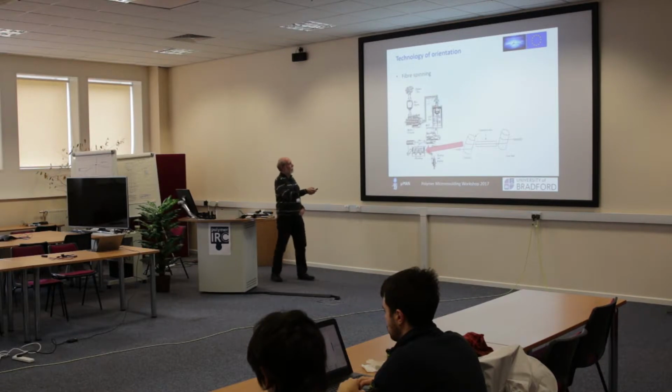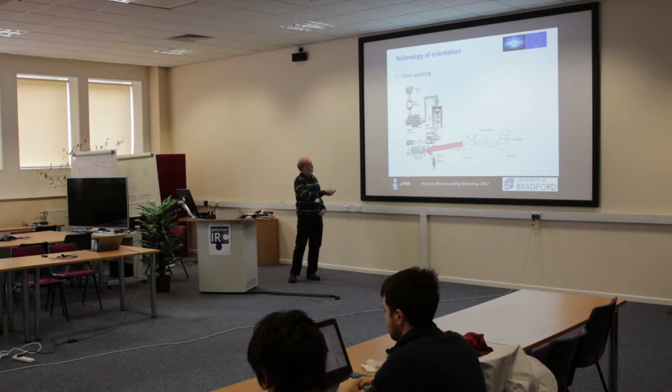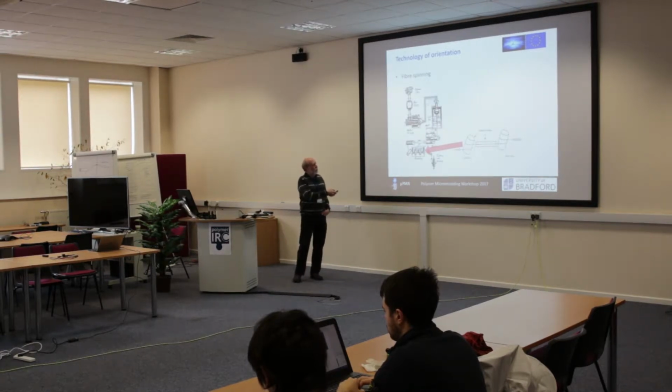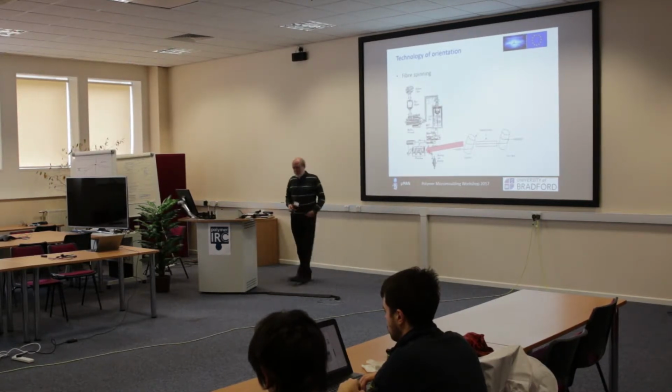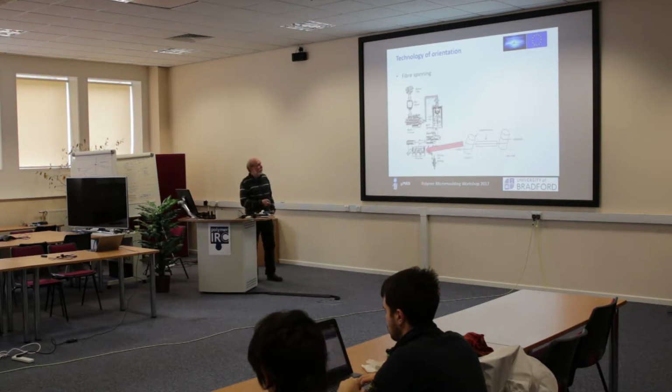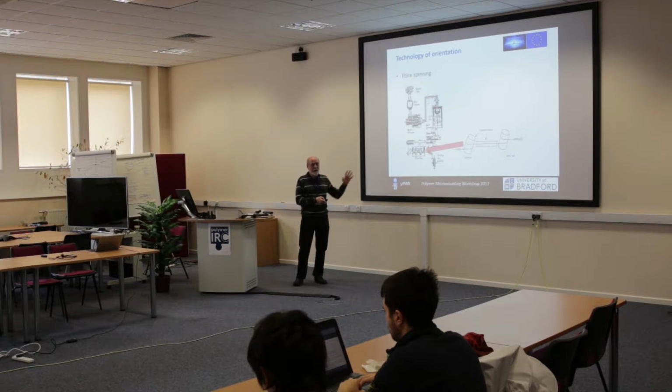At this point, you've got something like an isotropic fibre, without any drawing, without any molecular orientation. And this is the important part from the point of view of orientation. You've got two spinning rollers at different speeds, and you end up producing a permanent extension. And this is how you get the very high orientation.